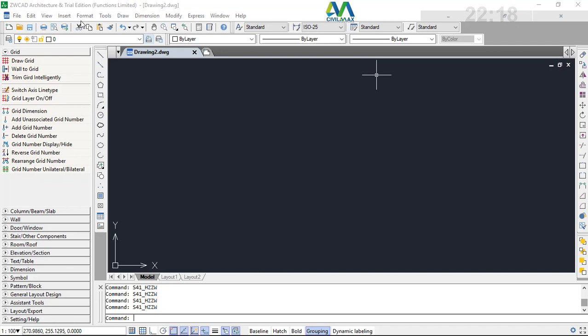Now I'm going to use this program to show you how to create the grid lines, placing grid dimensions, and also placing the floor slab, and creating also the raft foundation. Now we'll go straight away and get started here, and I'll take you through the